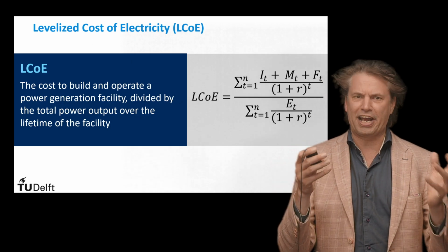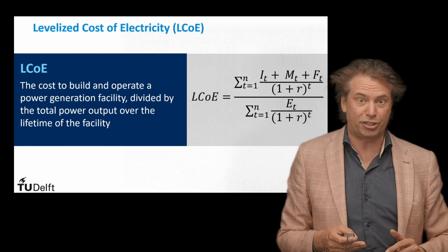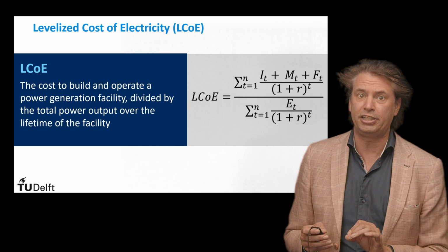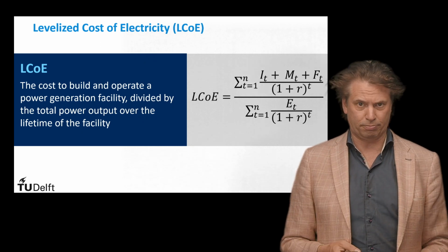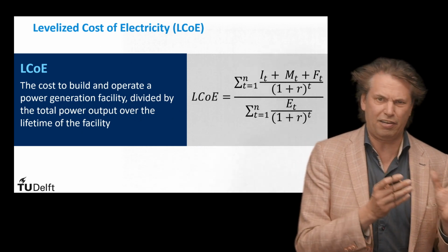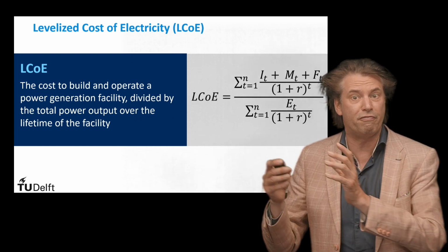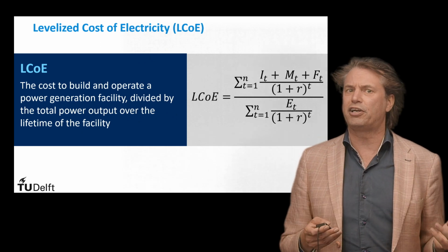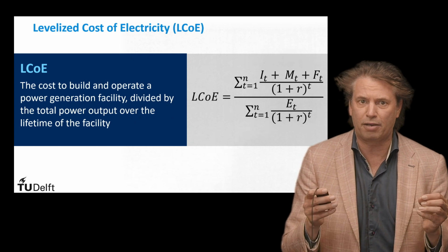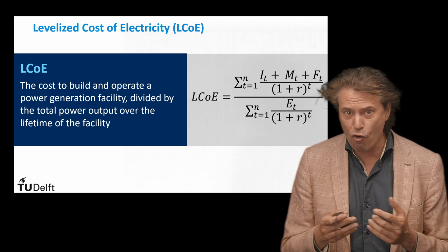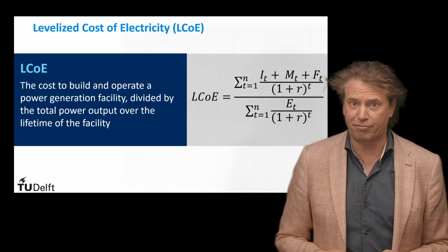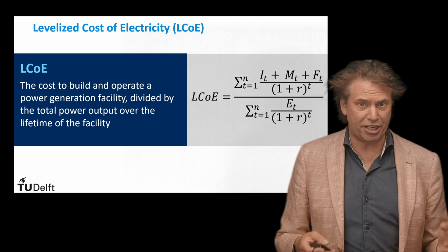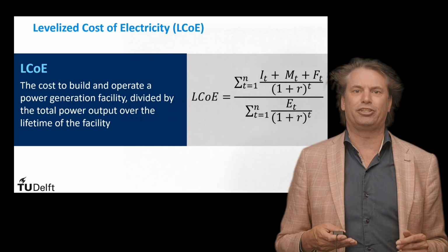Let us start by defining the levelized cost of electricity, or LCOE. The LCOE is defined as the cost per kilowatt hour of electricity generated by a certain energy system. It is generally used to compare the lifetime cost of project based on the various power sources. For the levelized costs, the overall cost of an energy plant during its useful lifetime are calculated. Then the overall energy production of the plant over its lifetime is determined. Using these two numbers, we can then figure out the LCOE of a given energy system.